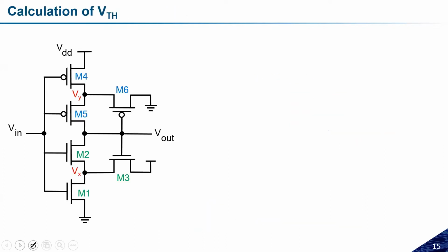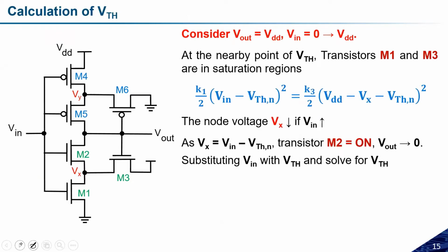If you see here, this expression, Vx is equal to V in minus VTH. Okay, so this V in, you are saying the extreme value, which is the VDD minus VTH. And that will be achieved at this point, and the transition is well before this point. So this Vx can never be like VDD minus VTH, and before that there will be some transition. Okay, sir. So this V in can never reach that; before that the transition will be there.